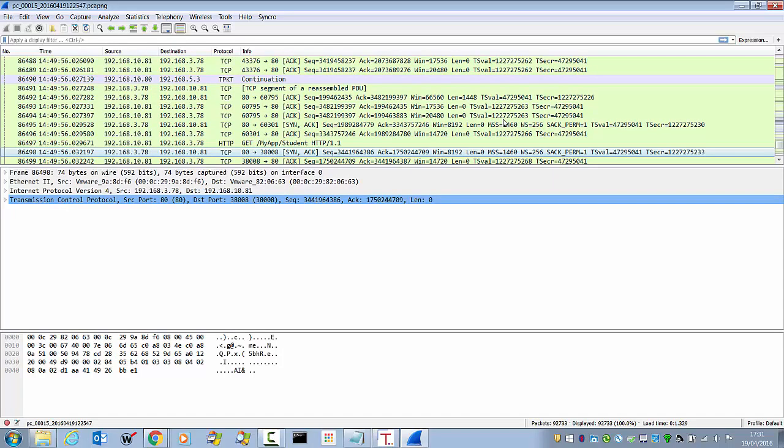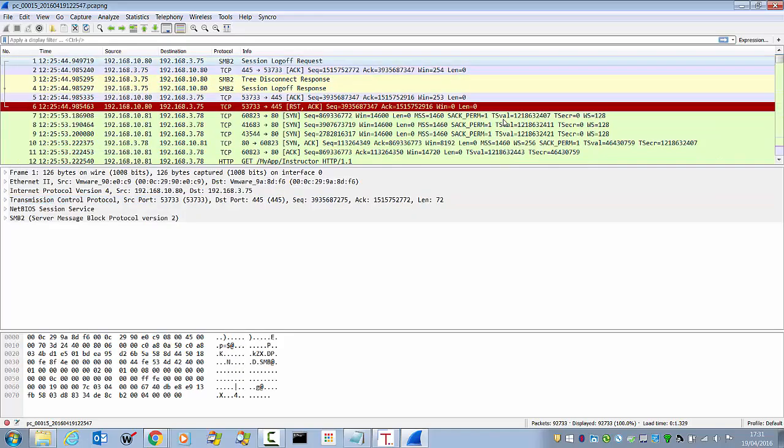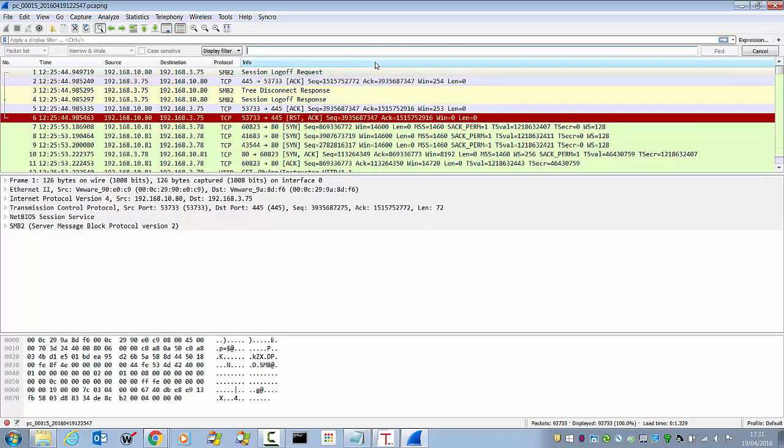Now I said that I'd show you how to find the marker without using Workbench, and as I've just lost where it is, we can actually test that out right now. So I'll jump back to the beginning of the file and I simply do a find, and I'm going to find for the marker string, which in this case was A7 if you remember, and I think it had question mark M equals 1.